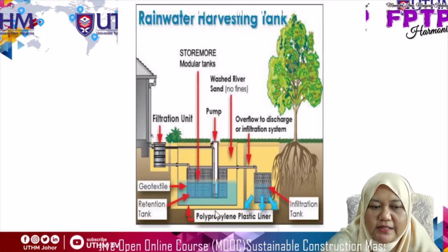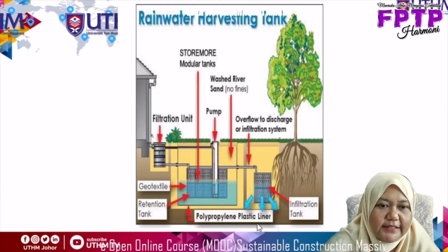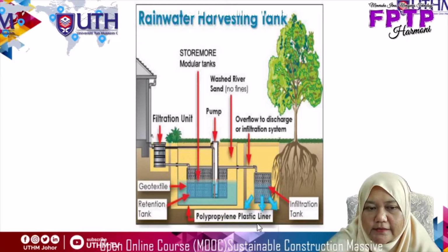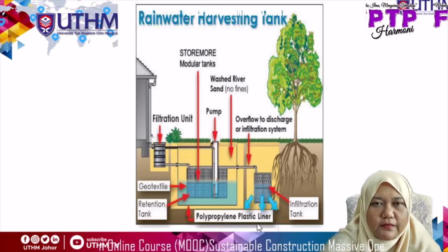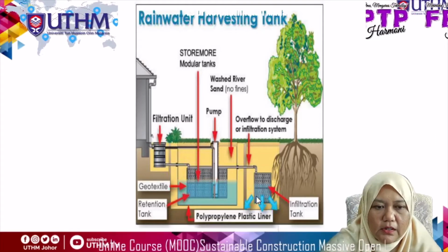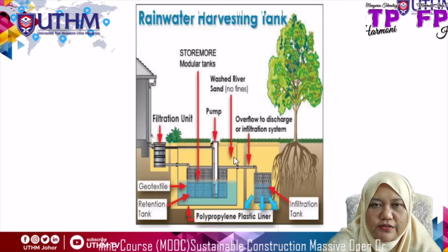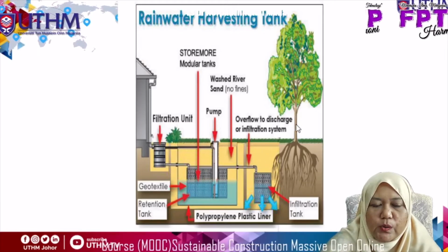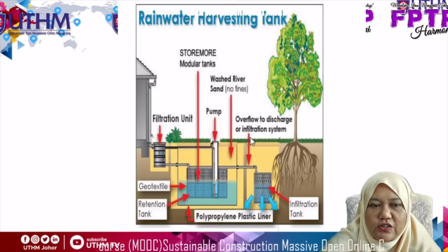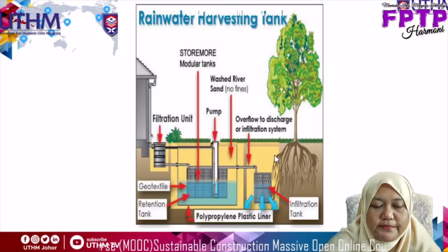It also has a polypropylene plastic liner to avoid infiltration. It also has washed river sand and an overflow pipe to discharge to an infiltration system.